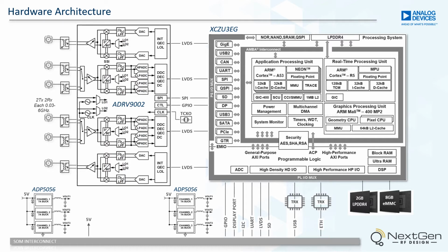Each receiver can be switched between 2 50-ohm 30 MHz to 6 GHz receive ports, allowing for optimal tuning or supporting one of the observation receive paths for digital predistortion and transmitter power monitoring. The 2 transmit ports support 30 MHz to 6 GHz with up to 6 dBm of continuous output power.